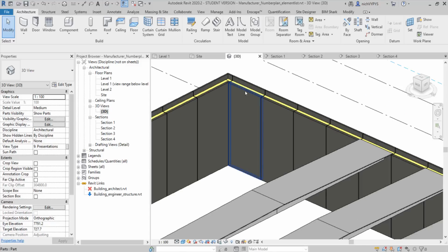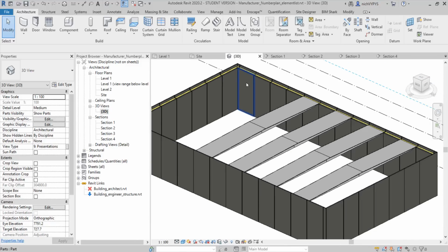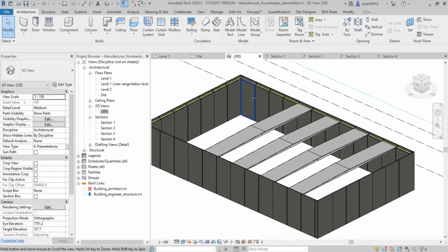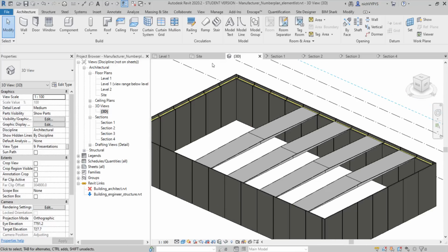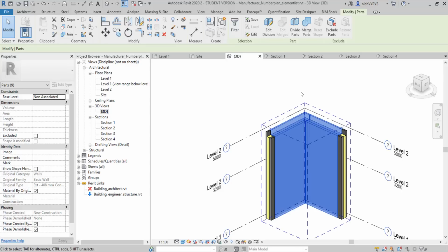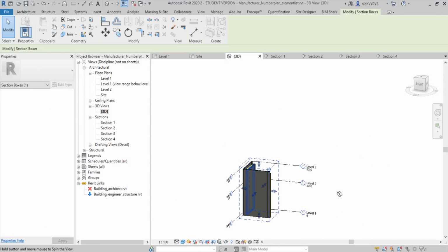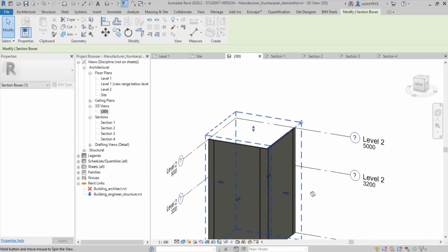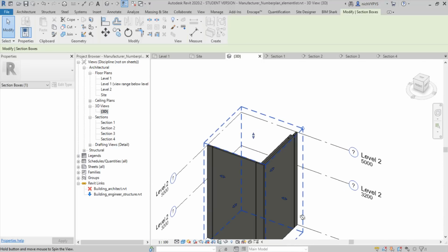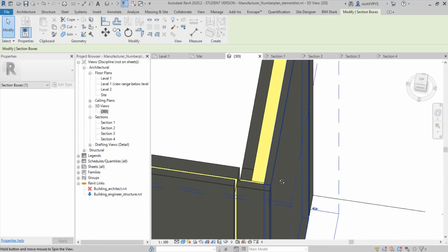So if I select those parts that we have around this corner and then make a special 3D view of that corner so I can see it better, then you can see I can begin to merge the parts that were split up before, because this corner actually came out of 2 original wall elements and I want to merge them into one.